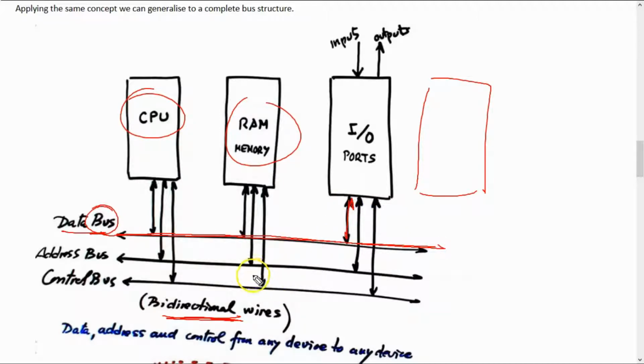So these copper wire connections are connecting everything. And sometimes, by means of another bus, the control bus, you can decide, for example, if the CPU is outputting data to an internal memory position, to write this data in a memory position, and later on perhaps you like to input from a port register, a port pin, through the same wires, just now in the opposite direction, to the CPU working register.